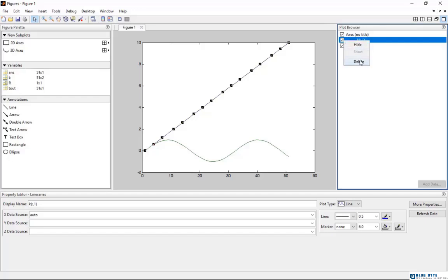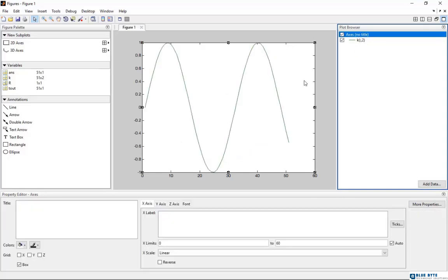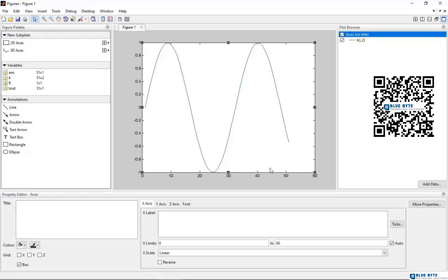As you know, here the simulation time was 10 seconds. But here the time dimension is divided into 50 parts. This is because of the Simulink sampling time. We should have some additions before saving it as array, but in the structure with time mode, we don't have a time limitation. Let me explain about this window.